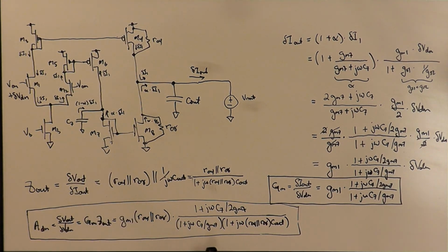And so we have two things going here that allow us to say something about the relative sizes of these two time constants, and hence at what frequencies these factors become significant. We have here a small capacitance times a small resistance, and we have a larger resistance compared to this one times a larger capacitance compared to this one. And so we get the sense that this time constant is going to be much larger than this time constant, and hence this pole will kick in at a much lower frequency than this pole, and this pole kicks in at 1 octave below this 0.